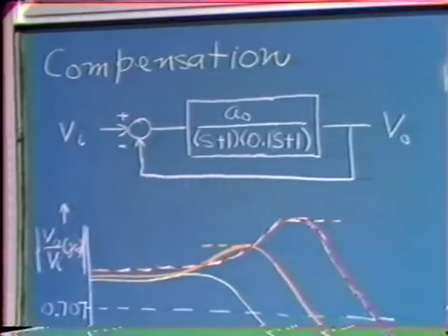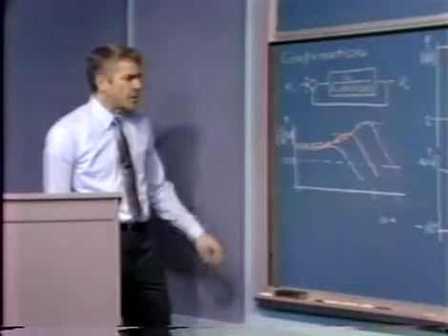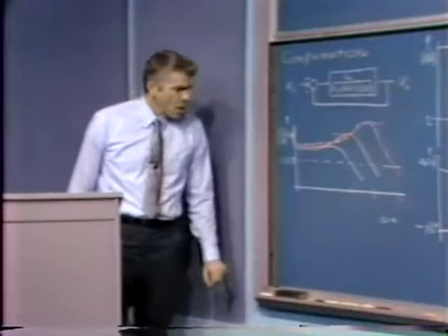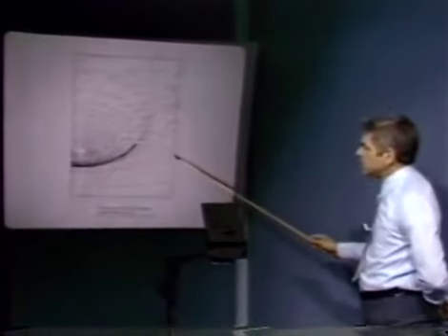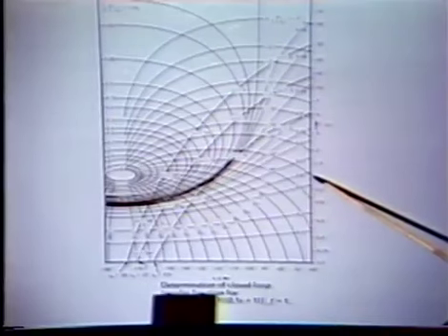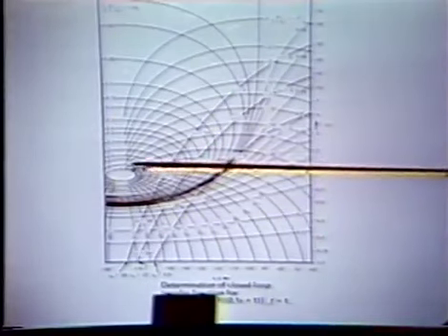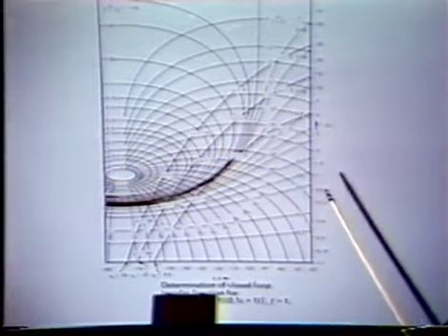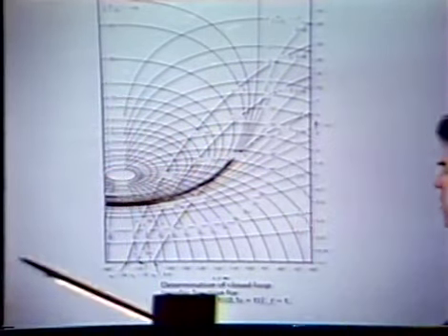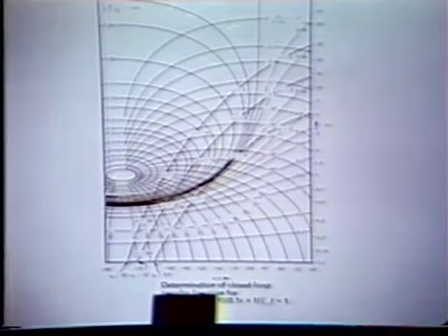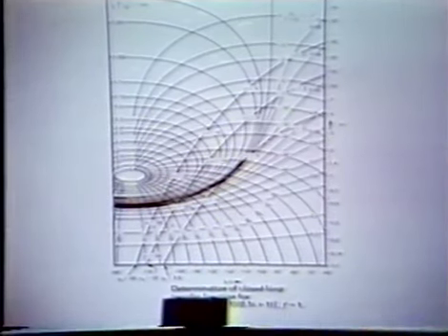And we'd like to look at the absolute stability of this system using the Nichols chart as our aid to evaluating absolute stability, or relative stability. Well, in order to do that, we go ahead and focus on the corner of the Nichols chart that's of most interest to us, in particular the part that lies near a magnitude of the loop transmission of 1 and an angle of the loop transmission of minus 180 degrees. So we focus on this corner of the Nichols chart.